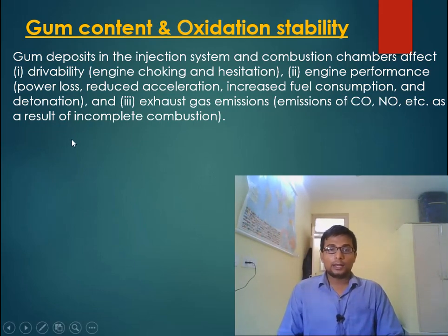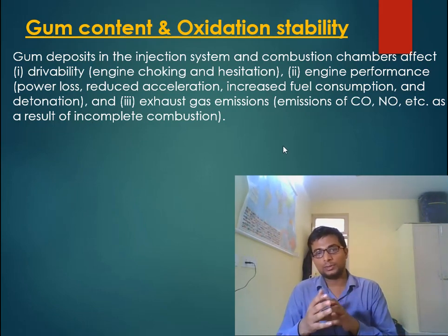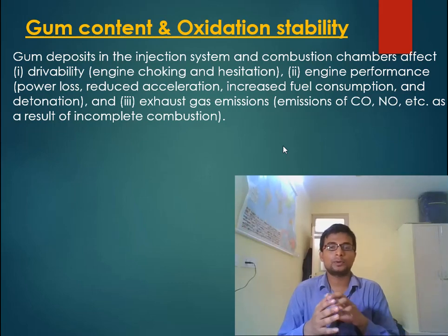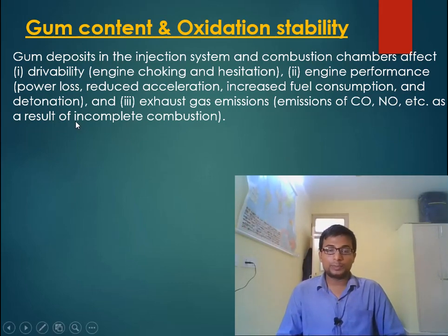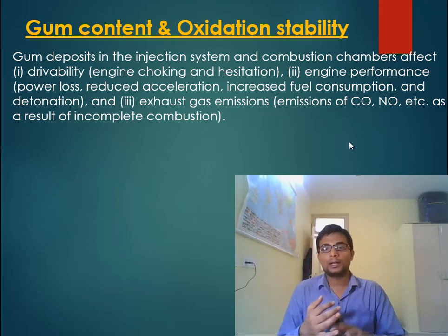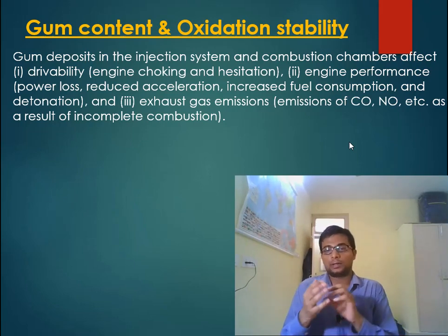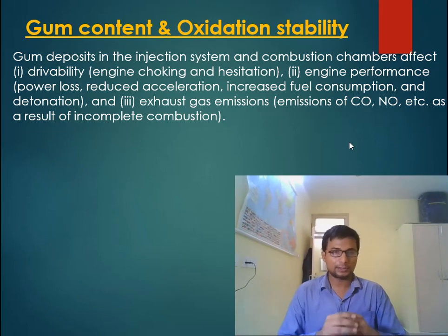Anyway, as I discussed, whenever there is solid deposition inside the combustion chamber, it may form a hot spot, and ultimately it may cause detonation or pre-ignition. So the octane number requirement will also increase. Ultimately, in exhaust gas emission, it may be the reason for emission of carbon monoxide and other unburnt hydrocarbons because of this disturbance in the air fuel mixture.